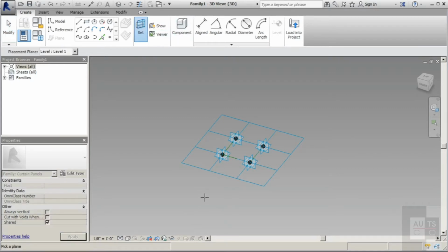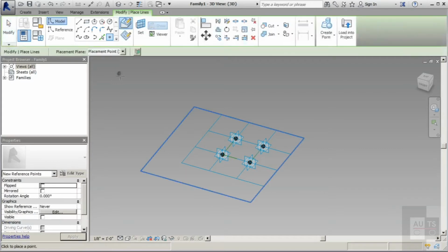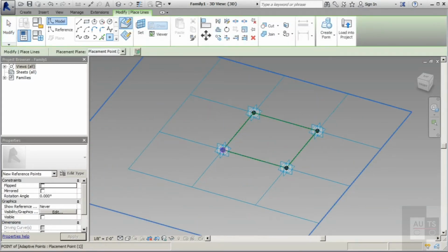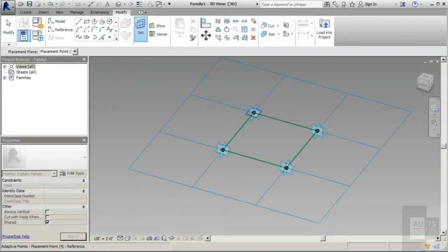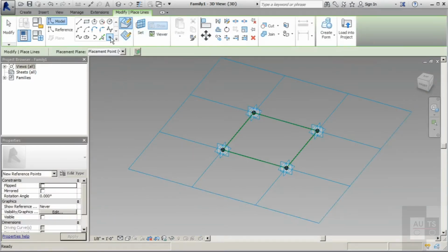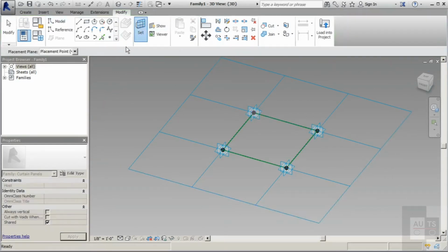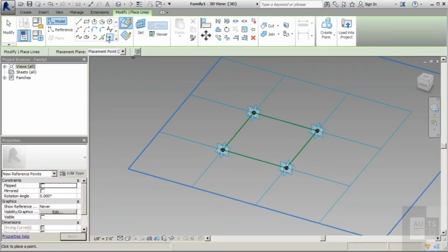And basically, at each one of these points here, we are going to place a point, and we're going to offset it and create the structure for our roof. So I'm going to set this work plane, and I'm simply going to place a model point right at that point. And I'm going to do the exact same thing for the rest of the other three. Set the horizontal plane, and I'm going to go with my model point element there and place it there. Set and place my point. Set and place my point.